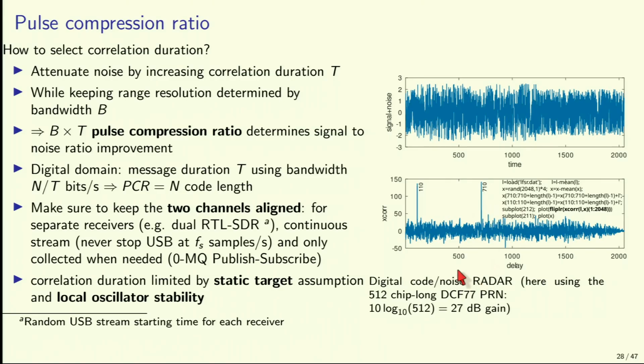So it's a very important concept because it allows you to raise the signal above thermal noise, or noise in general, and actually it means that if you're doing noise radar, you can emit below the noise, and no one will know you're emitting because you're under the noise. So I know people are doing this with geostationary satellite as well. As long as you're broadcasting below the noise, no one will detect you, and you're the only one who knows what is the pattern that you're broadcasting, so you are the only one who can detect these backscattered signals.